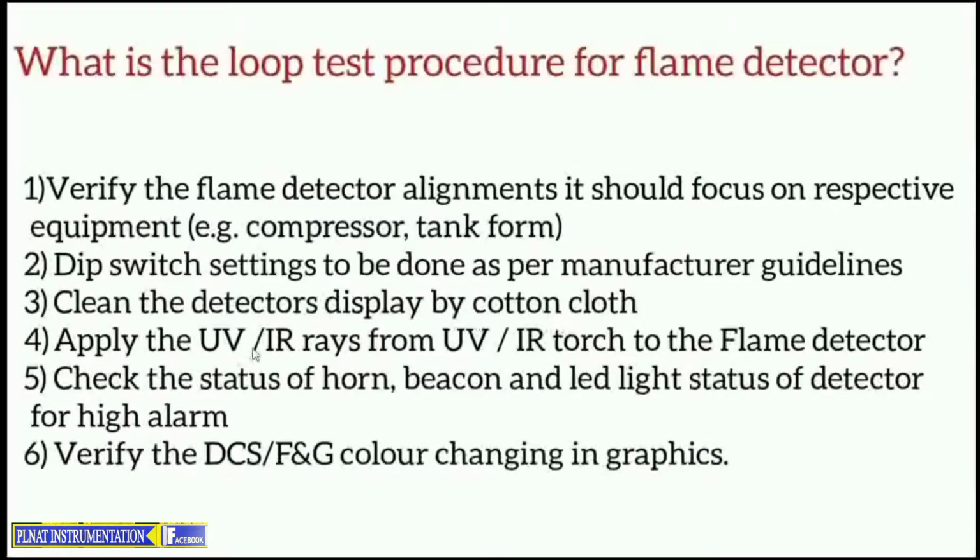Apply the UV IR rays from UV IR torch to the flame detector. Check the status of horn, beacon and LED light status of detector for high alarm. Verify the DCS fire and gas color changing in graphics.